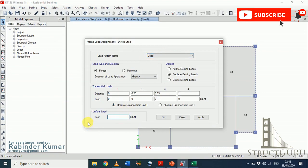So how to calculate the wall load? As we know that our height of wall is 10.5 feet multiplied by density of wall, if I am considering cement concrete block, so the density will be 0.145 kip per feet cube, and our thickness of wall is 0.75 because our outer wall dimension is 9 inches. So the exterior load of wall is 1.141 kip per feet. So click OK.